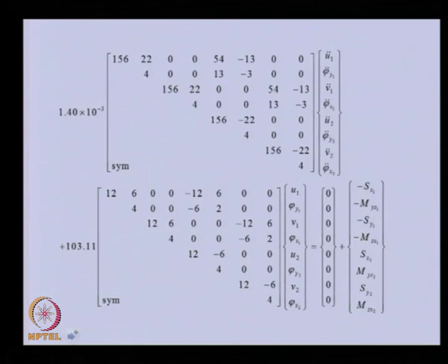and they can be combined. So, this is the elemental 1 equation when we are considering both plane motions. So, you can see here the first 4 correspond to node 1, horizontal plane, vertical plane. Similarly, this is for node 2, horizontal plane, vertical plane. Mass matrix, stiffness matrix, there is no external force. These are the reaction forces and moments.